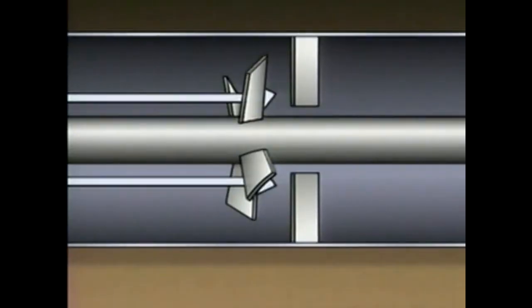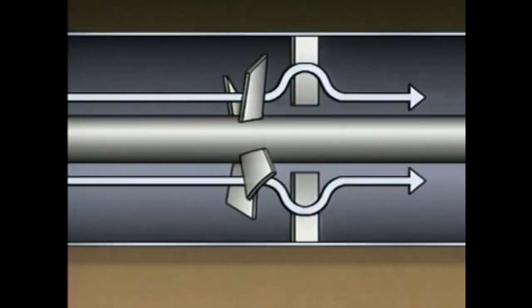The rotating blades then push the gas towards the stationary blades. When the gas contacts the stationary blades, they cause the gas to change direction as it flows toward the compressor's discharge. This causes the gas to slow down. As the gas slows down, its pressure increases.